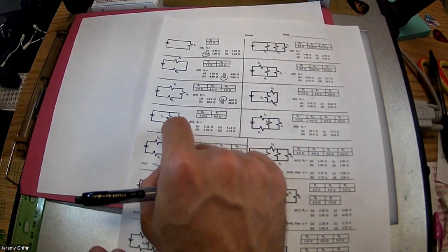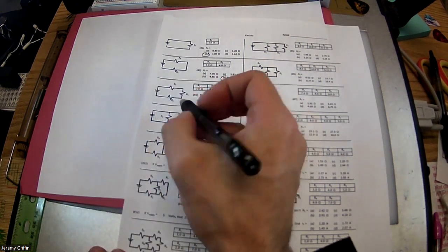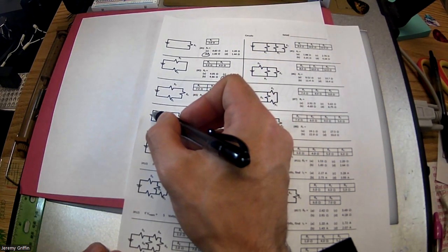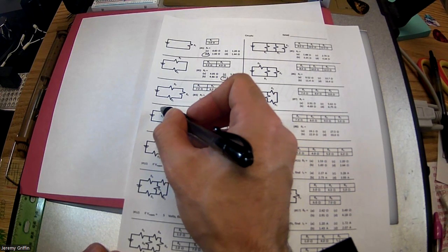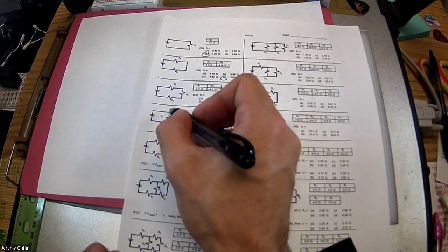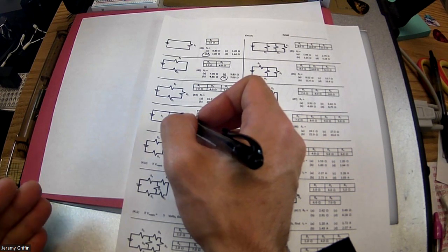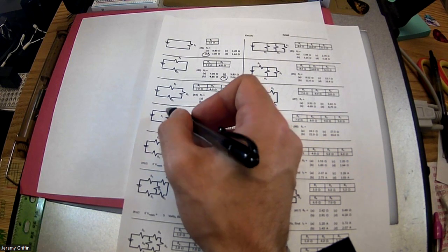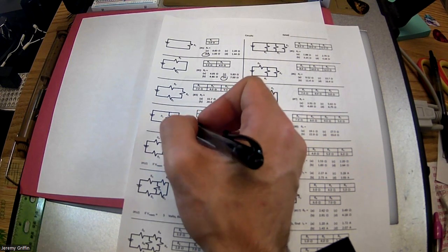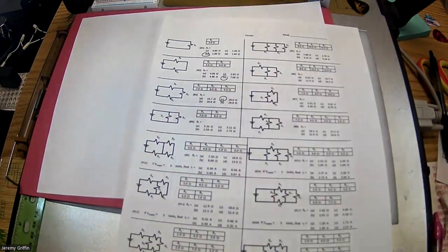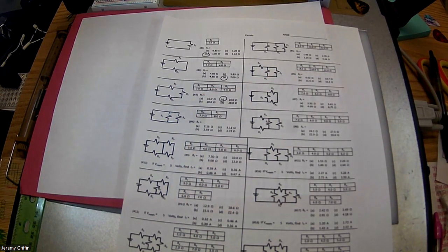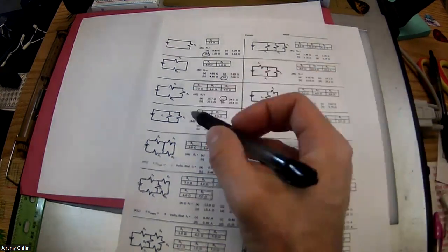Number 4. How are those 2 resistors wired? In parallel, right? Because here's one way to think about it. What would give it away is if you're driving around, you hit this junction, and then the traffic splits. So the current has to split, and not all the current's going to go through both of them sequentially. No. It goes through both simultaneously. Some of the current goes through only that one. So the other current only goes through that one, right? Okay. So the question again is, what is the equivalent resistance as perceived by the battery?